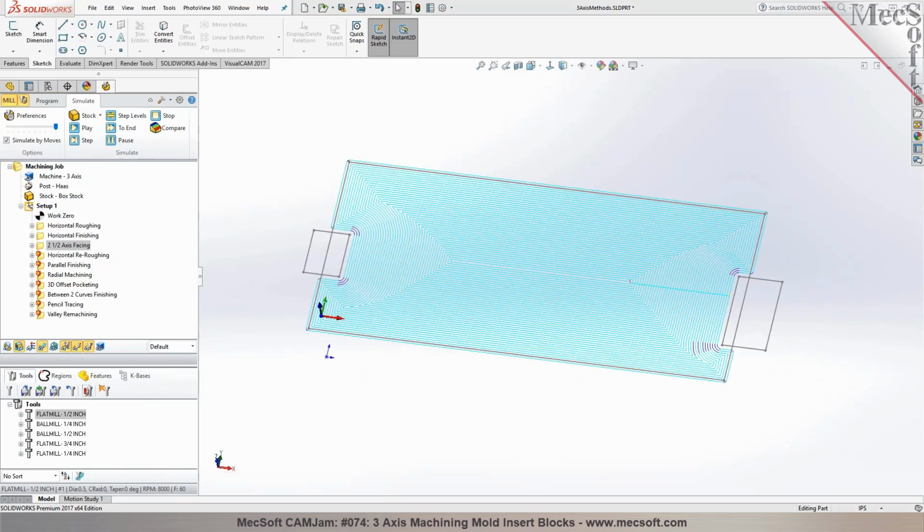Okay, so spots where the clamps are, let's say we're still in first setup, but we want to clean up those areas after. Okay, so you just want to go back and clean up these areas in here, so you could program a toolpath just for these areas as well, so you can define a boundary to program those areas. So if I had a clamp in here, for example, in the solid model, and I would like to go back and profile cut these areas, I can suppress this feature and go back and machine those areas out.